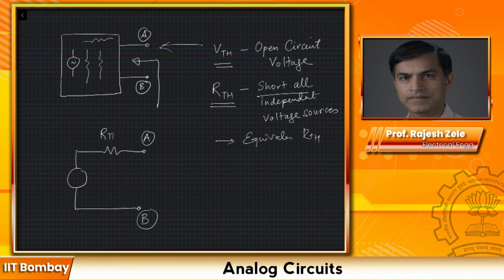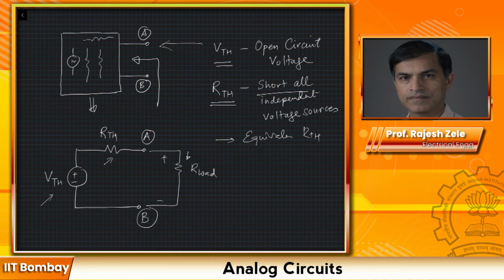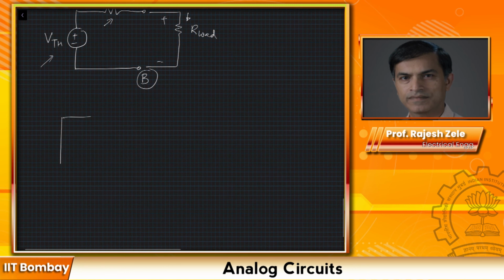And then you can model these complex circuits as simply as this. Okay, you can say this is my equivalent circuit, point A and point B, and this would be RTH and this would be your VTH. As far as you are concerned, this is the way this complex black box, which could have hundreds or thousands of elements, a network of elements, is going to look. And now we can connect our load resistance, and then you can work out what current we would expect. So again, Thevenin's theorem helps you simplify a complex network and represent it with a simple voltage source and a resistance.